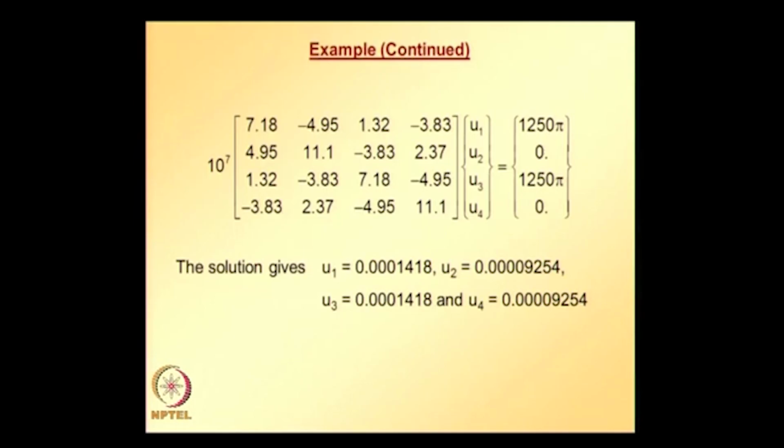And here calculations corresponding to one integration point will be shown. If you need to calculate stresses and strains at any point other than an integration point, we need to know the corresponding values of S and T at that point corresponding to its R and Z coordinates.